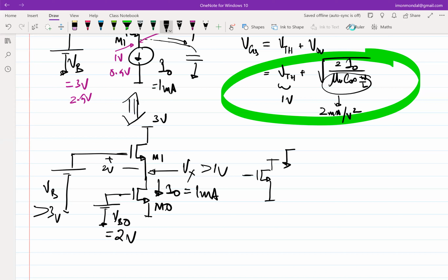Can you elaborate? He's saying no path for the current to go. Meaning there is current path, right? Extra current or reduced current can go or come from. Right. So his argument is if I increase the W by L of M1 and I assume that the current has increased, that extra current cannot go anywhere. Right. So any other comment from anyone? Is that argument valid?